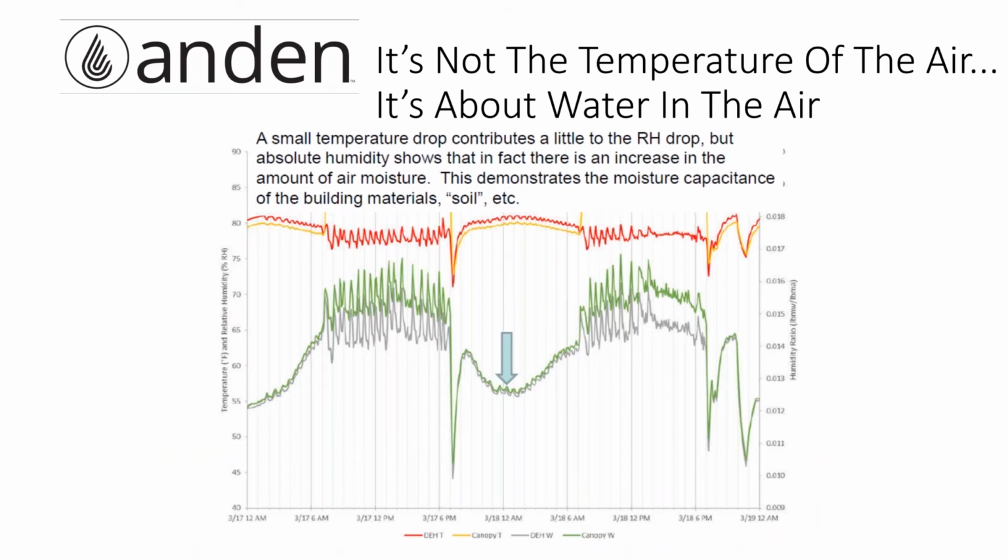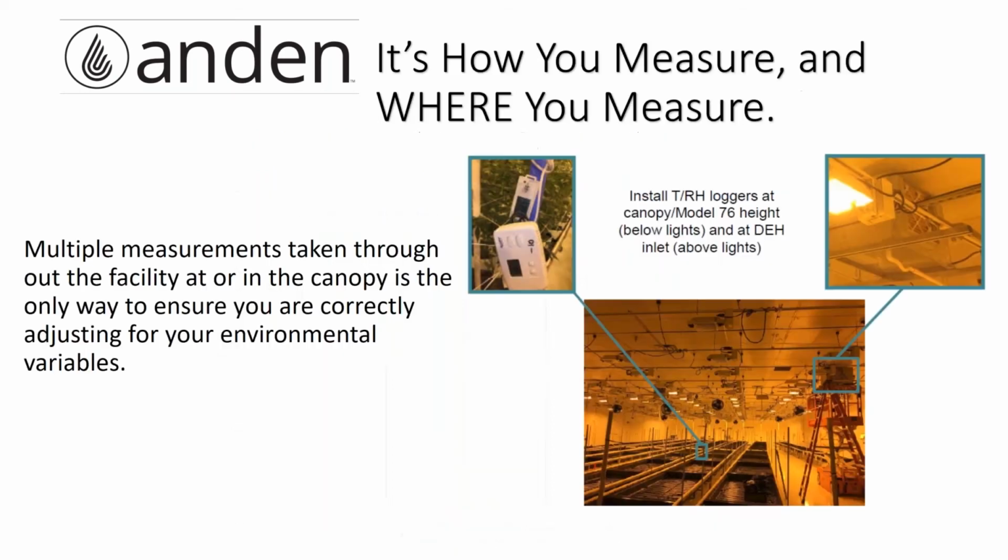And if we do that over time, and we can accurately calculate the correct temperature for growing and the correct amount of water for that grow based upon what your individual recipes are, we can really well control a room and massively increase the yield. And you do that by having equipment that can modulate with the temperatures inside of the room, and you combine that with measurement devices that are capable of measuring inside the canopies, not around the canopies, so that you are sure that you are flipping the VPD where the plants are, not just balancing out that room. I cannot stress that enough.